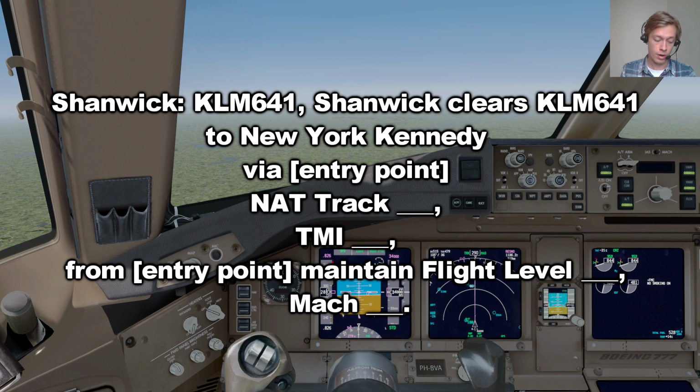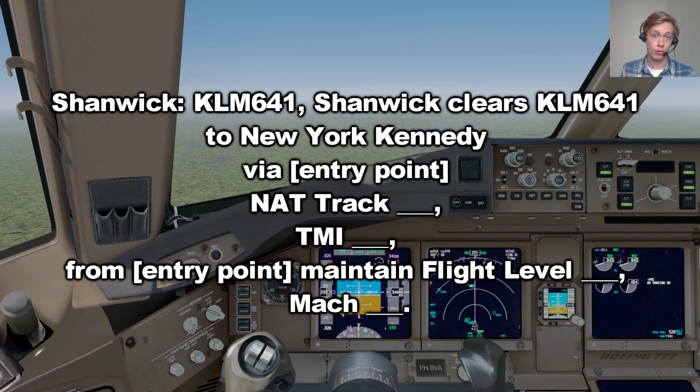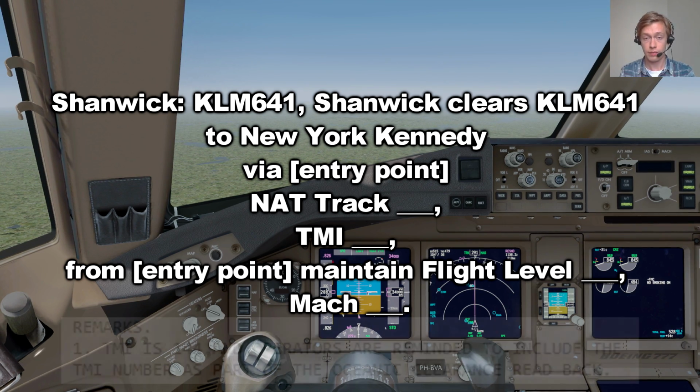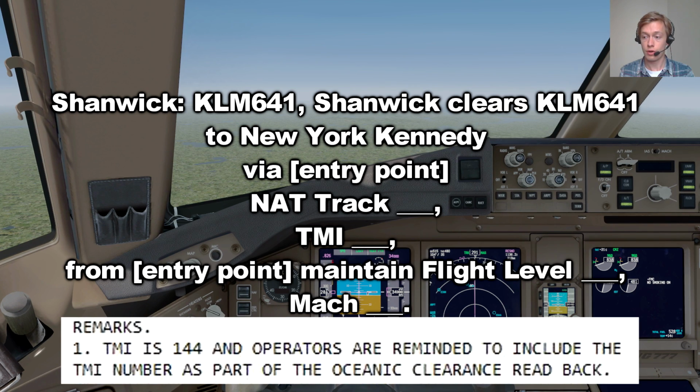And by reading back the TMI number, you don't have to read back all the separate waypoints of the NAT track. Now you can find the NAT TMI number in the NAT Track Message again. At the bottom in the remarks section, you will see that the TMI is 144, and indeed you are reminded to include that in the Oceanic clearance readback. Okay, so TMI is 144,